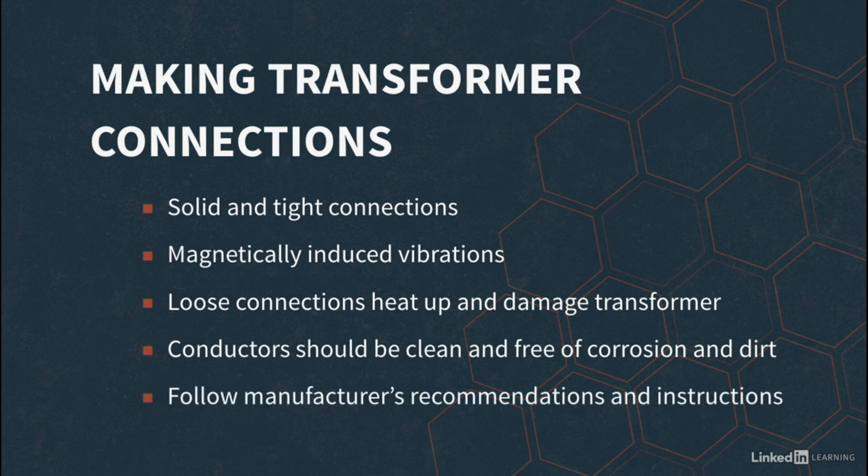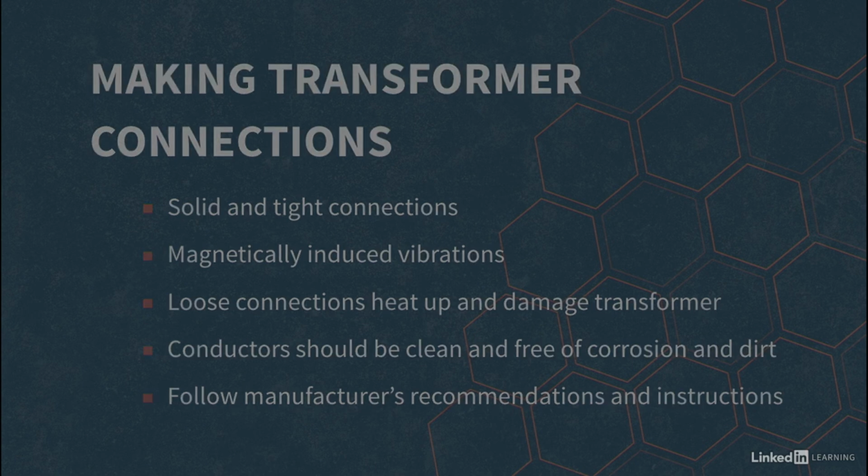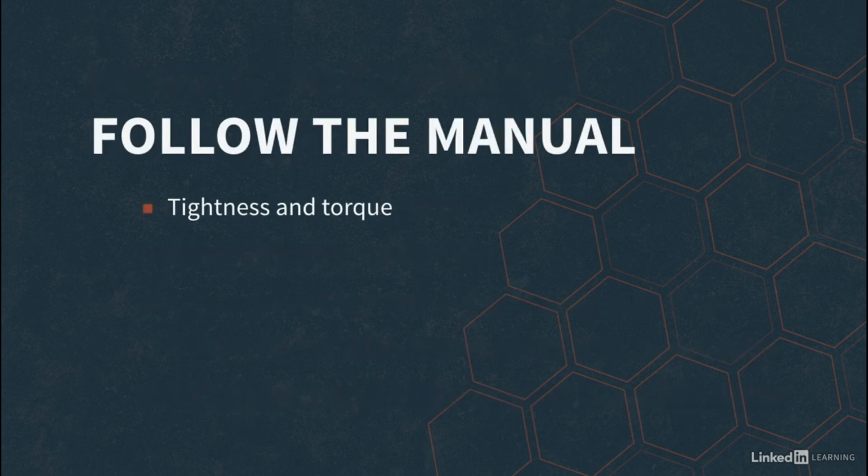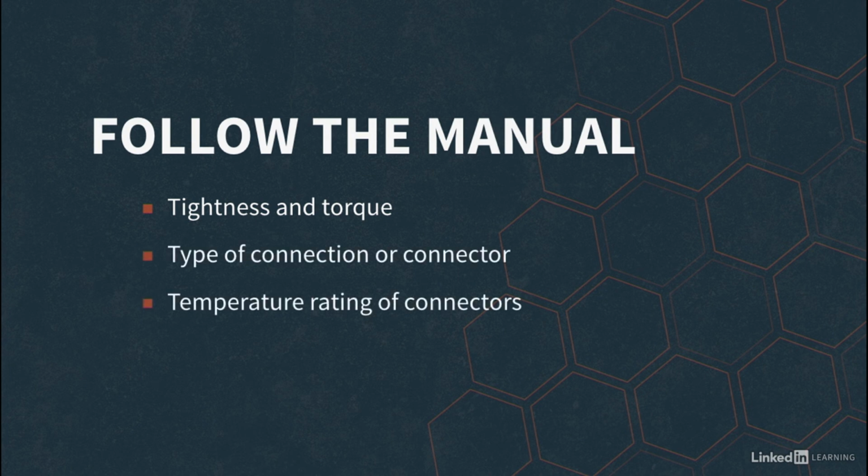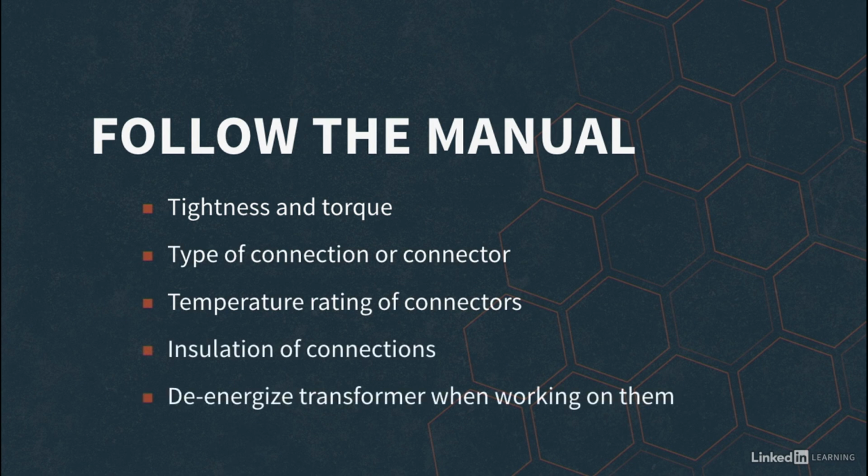Be sure to follow manufacturer's recommendations and instructions when making transformer connections for items such as tightness and torque, type of connection or connector, the temperature rating of connectors, and insulation of connections. Transformers should be de-energized when you are working on them if at all possible.